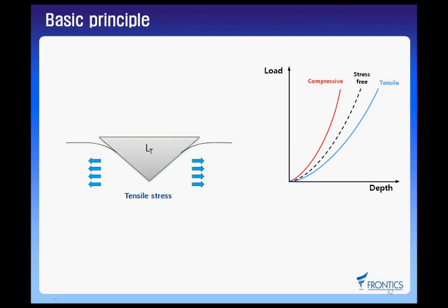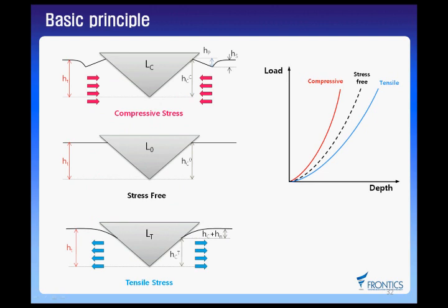With the same indentation depth, the effect of the load varies depending on stress state. A load gap relative to the stress-free state occurs due to residual stress. Finally, the load gap is applied to the general equation to evaluate the residual stress.